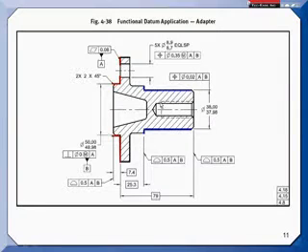On this part, these blue features could have been picked as datum features. I know a lot of people that would do that. They might make this diameter, let's say C, and they might make this shoulder D. And they might then put a perpendicularity on this shoulder with respect to C. Or they may not have called this out as D. They might just call this C and then say perpendicular to D. I probably wouldn't bother with that because when I put the mating part on here, it's going to hit the high point whether this shoulder is really perpendicular or not.